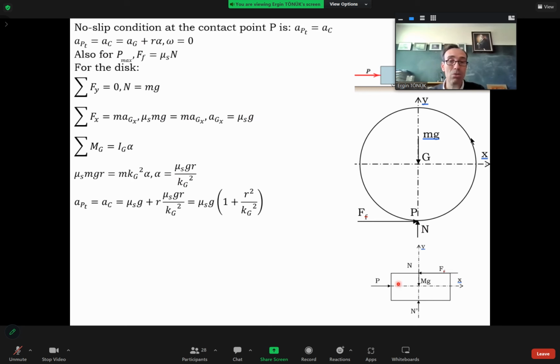When I draw the free body diagram of the cart, I will have the reaction force of this friction. Now, we should be careful with action-reaction pairs, okay? These two are opposite. I have the reaction of this N here. I have the weight of the cart, which I don't need. This is the ground reaction, which again, I won't need. This is my P. So what I'll do is, the acceleration of the cart times mass is equal to the sum of the horizontal forces, okay?